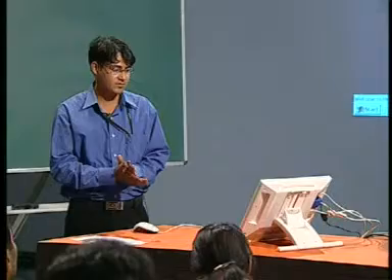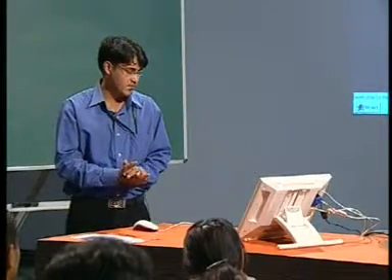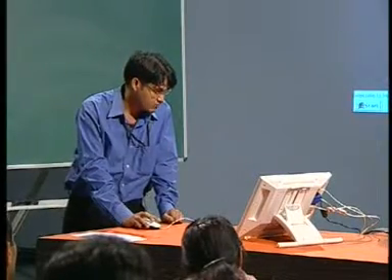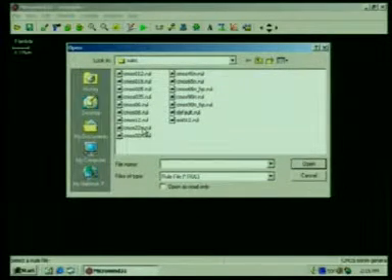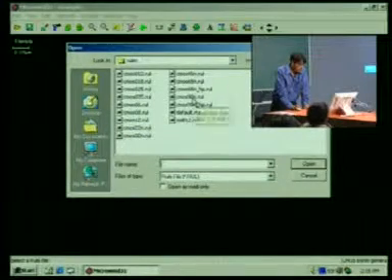Before any kind of layout, you need to first select the technology file, and since this is based on lambda rules, you have to set that lambda also. The first option is to select the foundry. These are the design rules. It has support up to 22 nanometer technology, and suppose I select this one, after that I just set this lambda value. What is this? This lambda is just equal to half of the feature size. This one is 65 nanometer technology, this is for 90 nanometer technology, so this lambda will be just half of that, 0.045 micrometer.